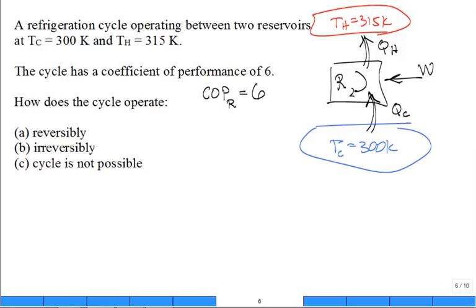All right, so somebody said, is the coefficient of performance refrigeration cycle the maximum? Is that 1 minus TC over TH? Is that true? Reversible heat engine. How about a reversible refrigeration cycle? Oh, that's this one. It's equal to TC over TH minus TC. How many people were looking for that equation and found it?